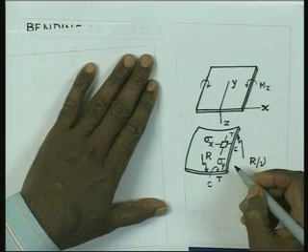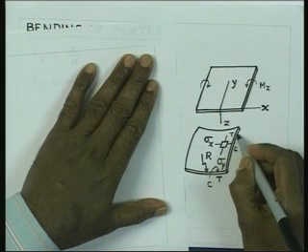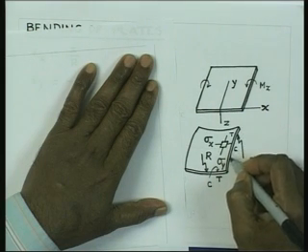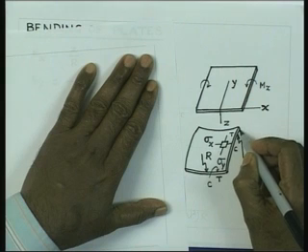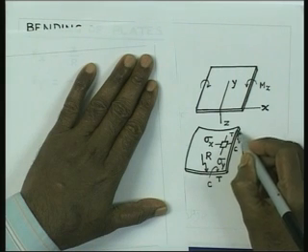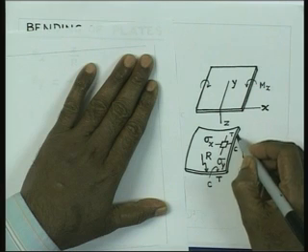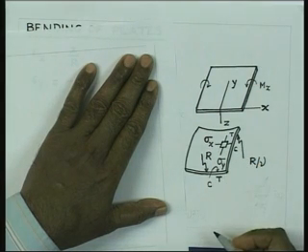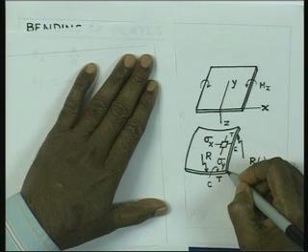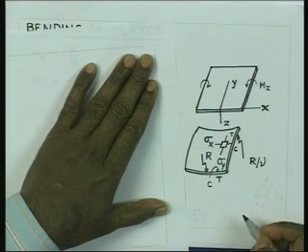Because of this, you find that the edges of the plate get a curvature like this, it does not remain straight. So, you have tension stresses there and compressive stresses there. So, it actually folds or rather bends like that. So, there is a curvature demonstrated by the plate towards the edges, and this curvature gradually dies down as we move towards the center of the plate.